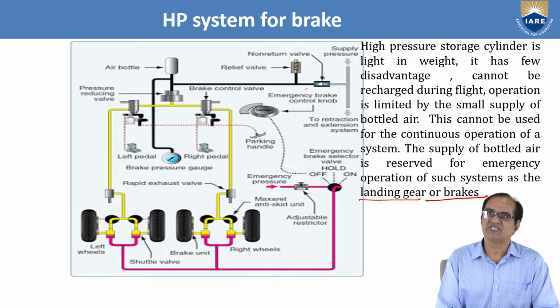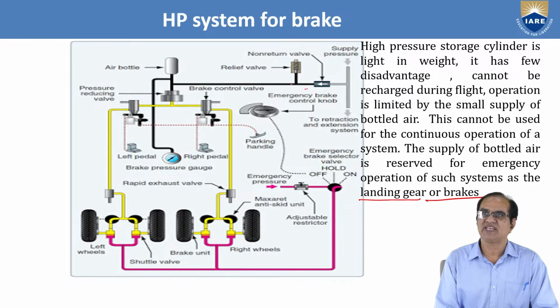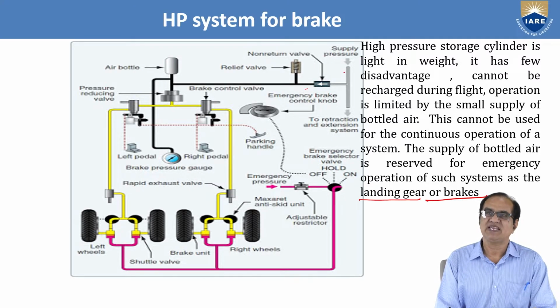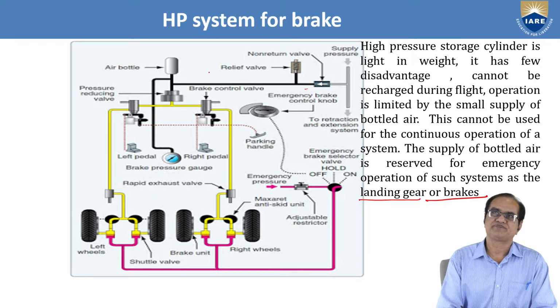If the pressure of this thing is higher than the required pressure of the bottle, the pressure will be released from here, and a net amount, whatever is required for the system, only that much amount of pressure will enter inside the air bottle. As and when air bottle is charged and it reaches the pressure as per the requirement, this relief valve will automatically cut this power supply and the charging system will be cut off.